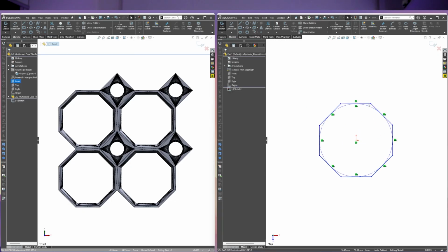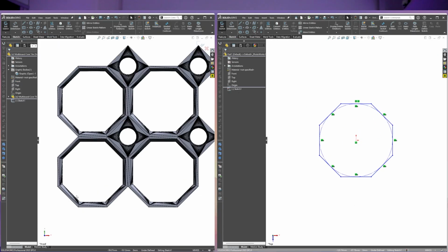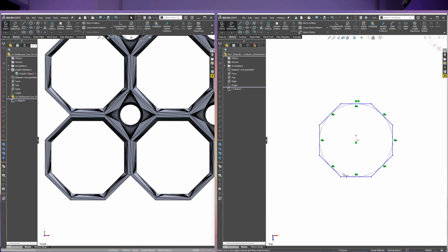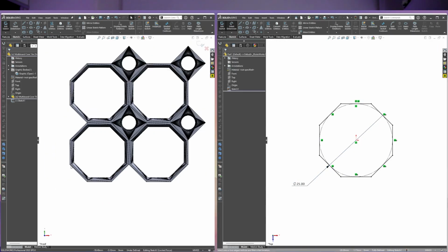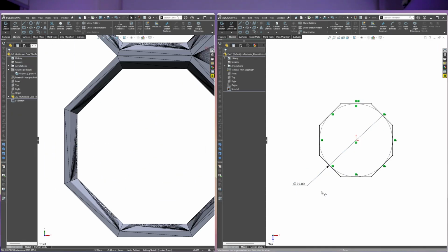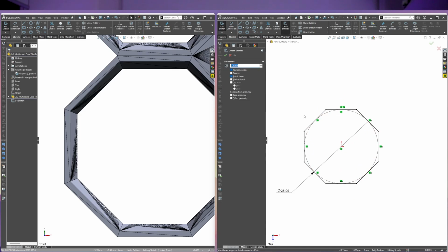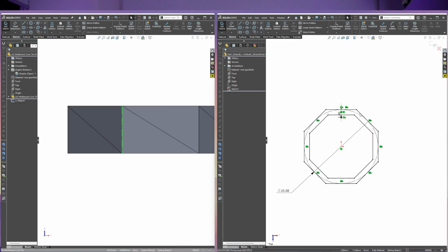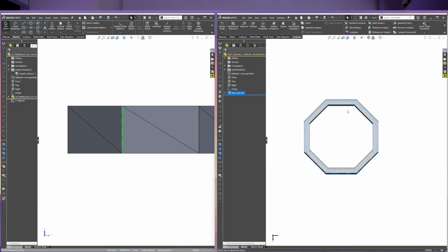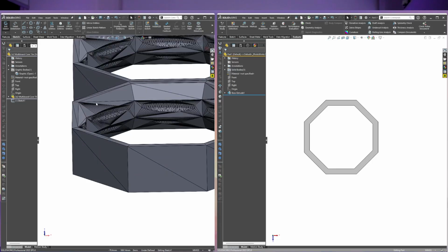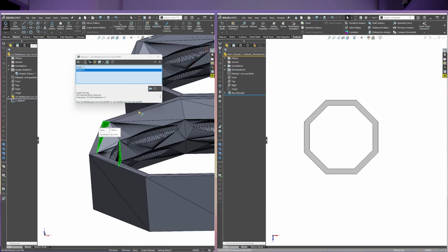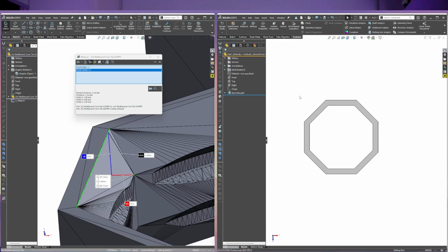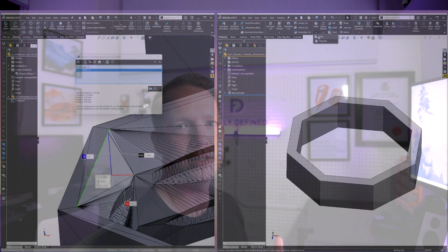So the process I'm going through here is I've already had a look at the geometry of the existing part. I've had a look at what I think are the kind of features it's built from. So I'm trying to assess, am I using extrudes? Where am I using cuts? Do I need revolves? What kind of complicated features like sweeps, helixes, threads am I going to need to do this part? So I'm trying to set all of that up and think about that as I'm going through the process of recreating the model.